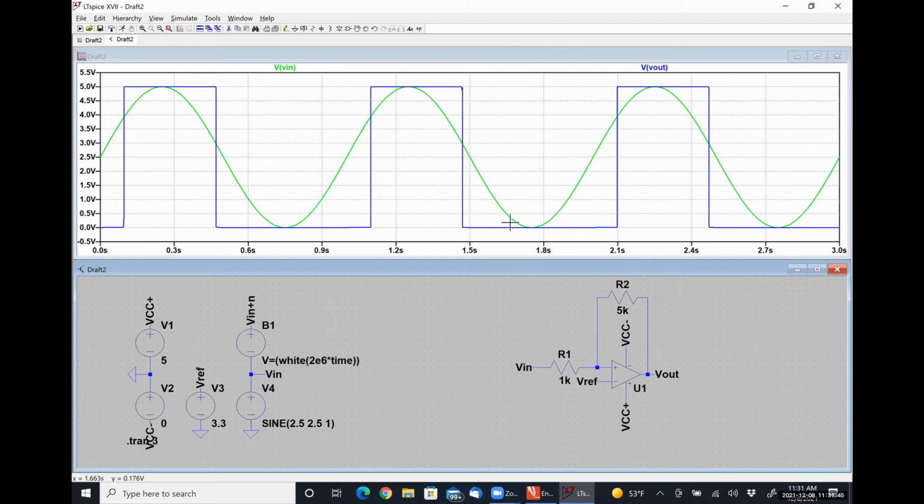It actually goes low when it's less than 3. So we have latching going on. The output is staying high until some secondary condition is met. And then similarly, the output stays low until Vn gets larger than this upper trigger limit. And it stays high until Vn gets less than that lower trigger limit, right?